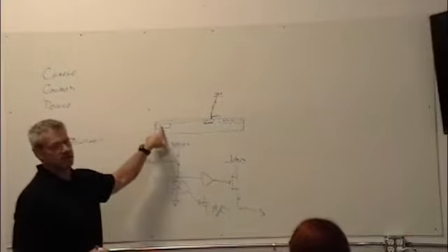Most houses don't have the capability to do a hydrogen passivation. One of the houses I worked with could. They would push hydrogen gas in and cook it in, and wherever these were, you get a hydrogen bond there. And that one electron, he would share, and he would be perfectly happy. But now, when you do that, you're creating a stress in the crystal structure, and you're doing some other things too that can cause some weirdness.